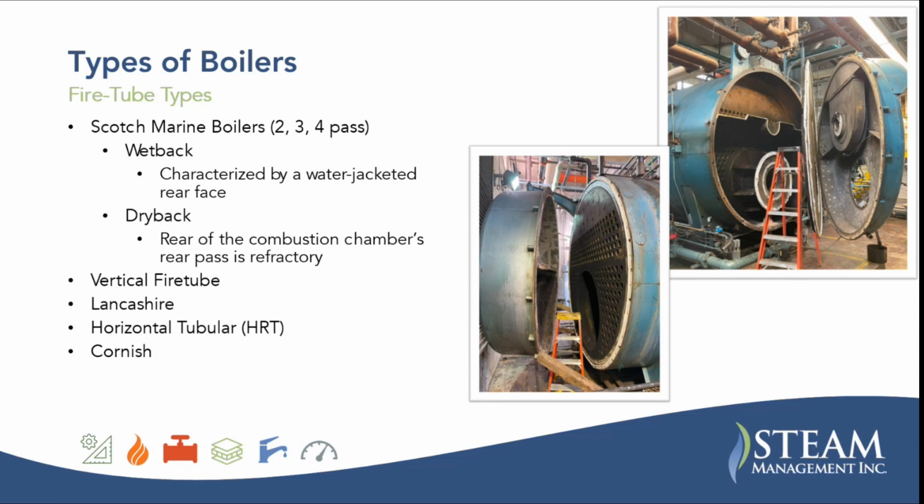I know that it's used for that, as far as like it's basically just a margin, right? So if you have considerations like that, then you can select a higher pickup factor. However, it is also accounting for losses within the piping system. And your losses to your pipe are generally going to be around 10% of your energy. So if you go from bare pipe to an insulated pipe, you're going to save around 90% of the energy that would normally be lost. So you're still losing that 10%. I guess it's not 10% of your energy, but you're still losing 10% of what would be lost from a bare pipe.